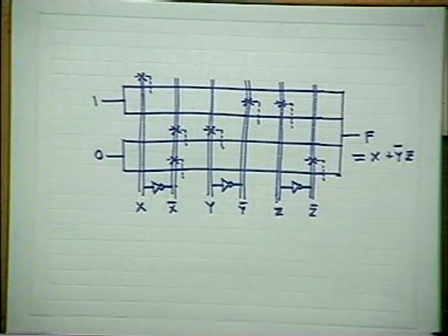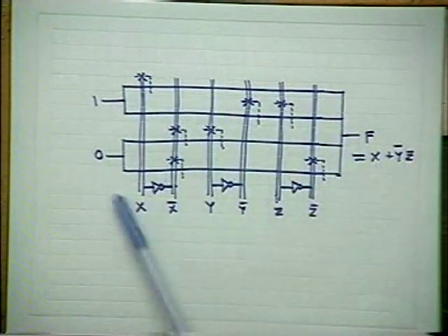This is a very simplistic kind of approach, but what is the major drawback? If it is a very large IC, suppose a 16-bit kind of thing with at least 16 output functions. The number of output functions is not a problem, but if the number of bits is too large, can you envisage the problem? Voltage degradation when using NMOS logic. Whatever I have discussed is NMOS logic, and the voltage degradation problem will be there. So you have to suitably adjust the areas of the transistors, and all these problems are there. Therefore, this is good only for a reasonably small circuit, not today's VLSI. When we are thinking of millions of transistors, this approach is not that good. So it was an intermediate phase. Let me tell you frankly, this pass transistor logic is very rarely used today.